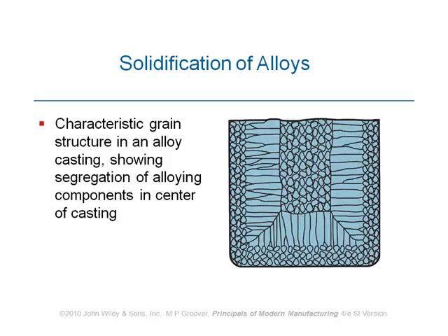Material will disintegrate. Meaning that those grains, say the melting point, let's talk about these grains first. In the core, we have got component A with a higher melting point. On the surface, we've got component B with a lower melting point. So what happens is that the surface of the grains will be melted while the core is still solid. As a consequence, those grains get disintegrated from one another. And what you get is a disintegrated material or part, which is not desirable.